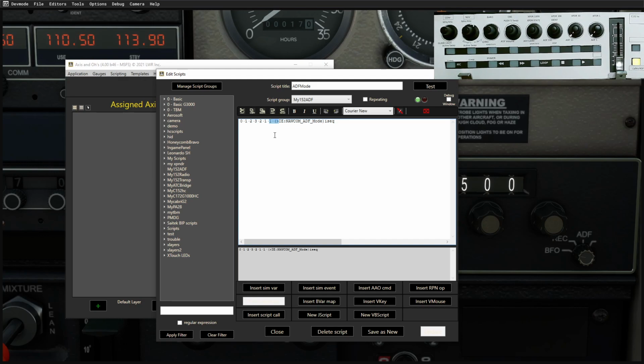So we need to edit this last little bit out here and tell it to read that as a variable. And we also need to tell the sequence here how many options there are. So how many inputs there are. It's 1, 2, 3, 4, 5, 6 different elements that it's going to step through. Now it's an index sequence.